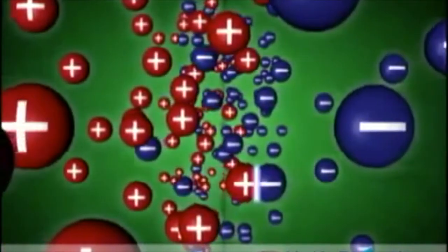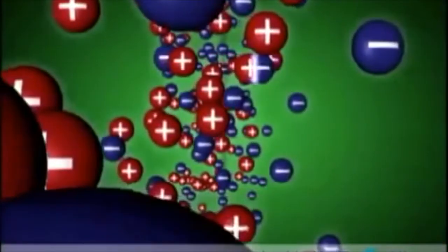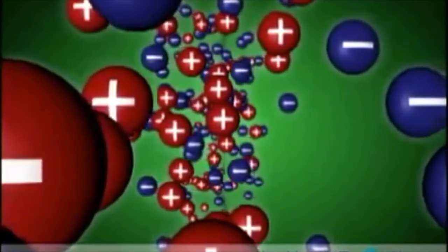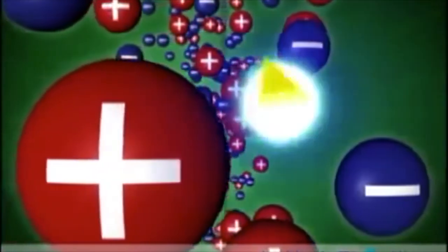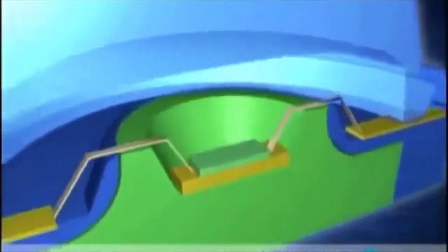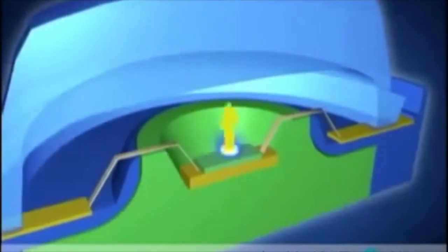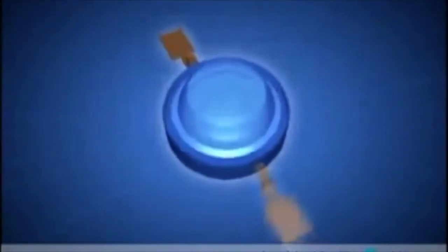The amount of photon energy released determines the frequency or color of the light. The type of material and process of creating the N-type and P-type materials dictate the color of the photons, as well as the efficiency and other performance characteristics of the LED. After processing the material into an LED chip, the chip is installed in a package that allows electrical connection and directs as much light as possible in the desired direction.